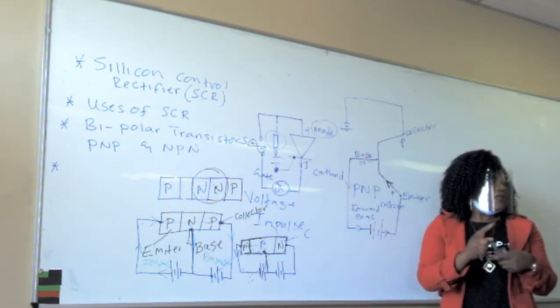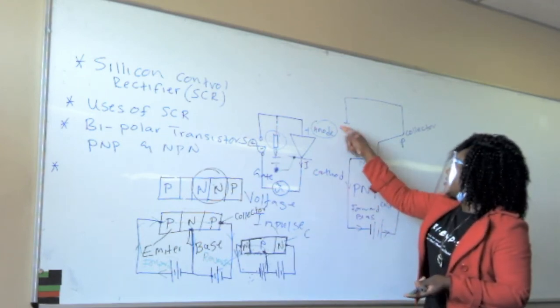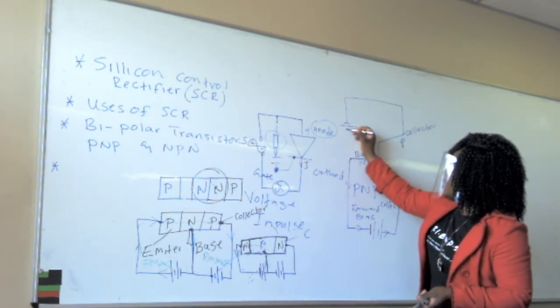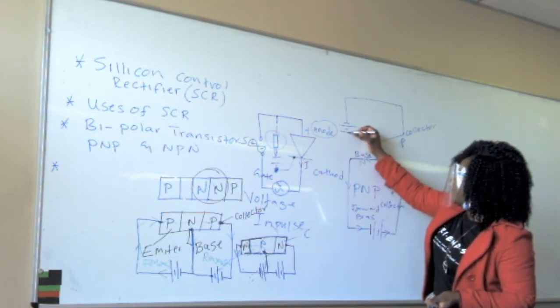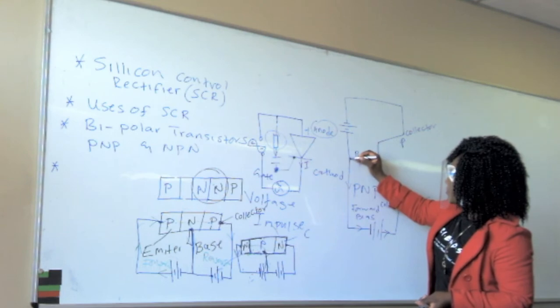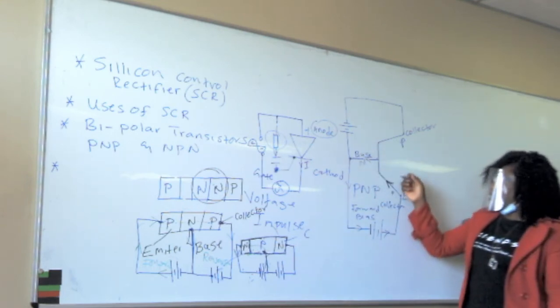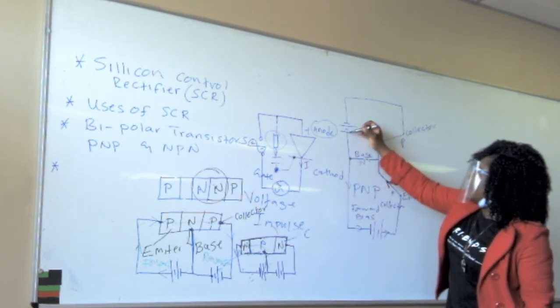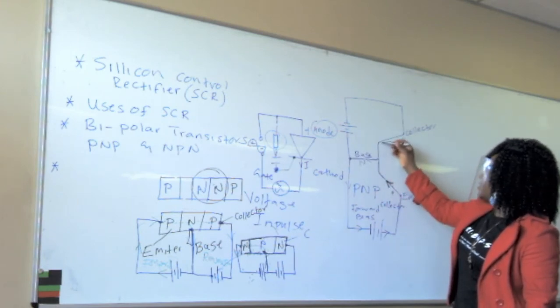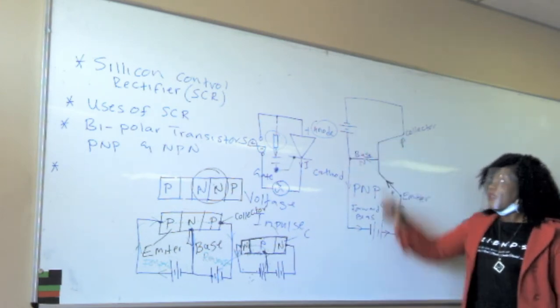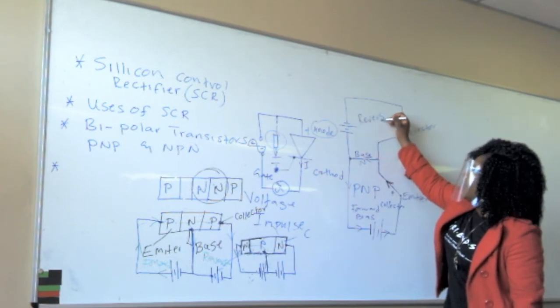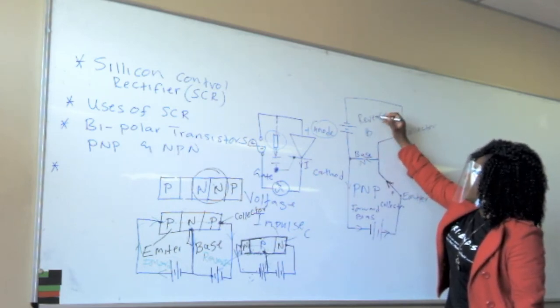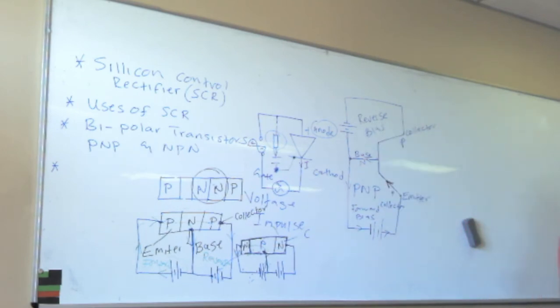We are trying to reverse. So it's negative, positive, negative, positive. The base is negative. It will be connected to the positive. And the flow of current, obviously, when it comes like this, one will go out that way. Here, current is supposed to be flowing that way, but it's reversed because this is positive, but it's negative. This portion here is reverse bias. Okay? And when it's reverse bias, we know that there is less current in that portion. That's why it is controlling. There will be less current in that portion.